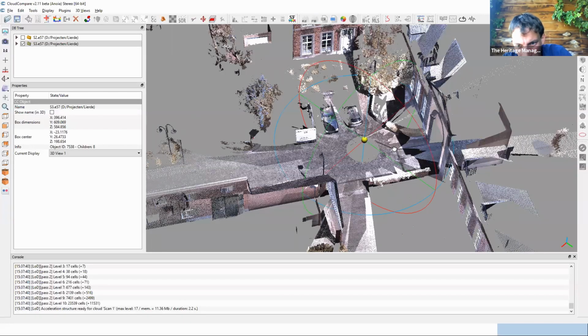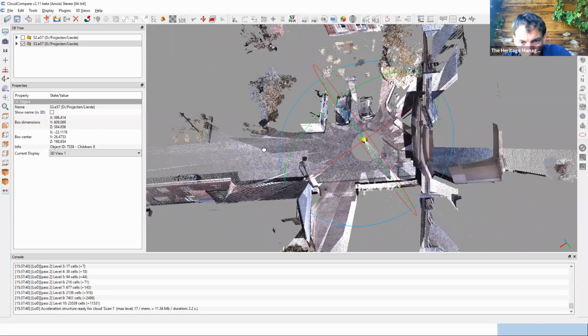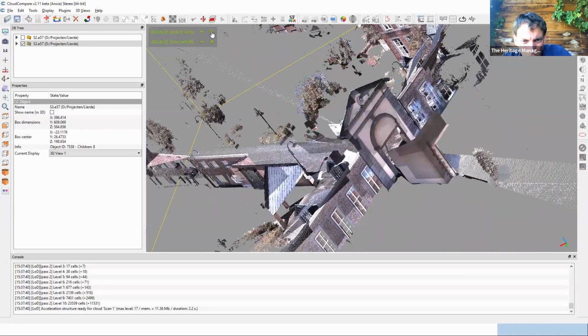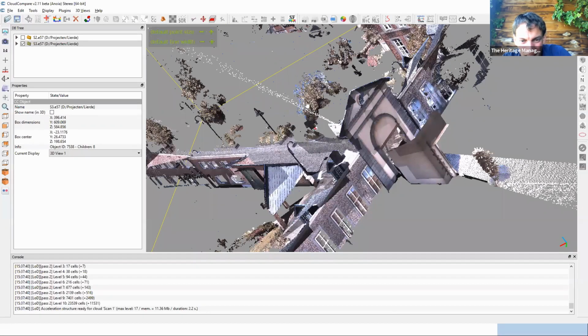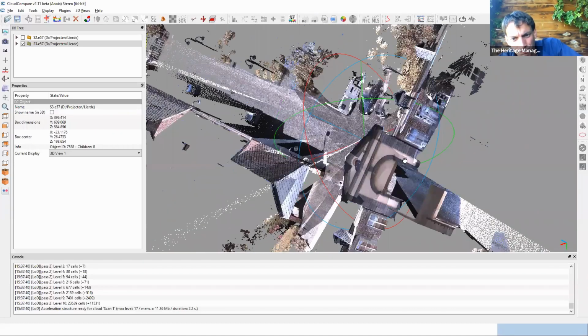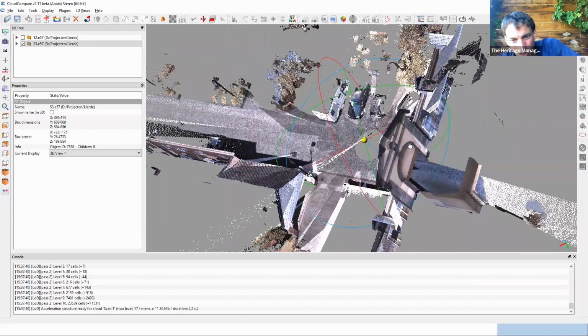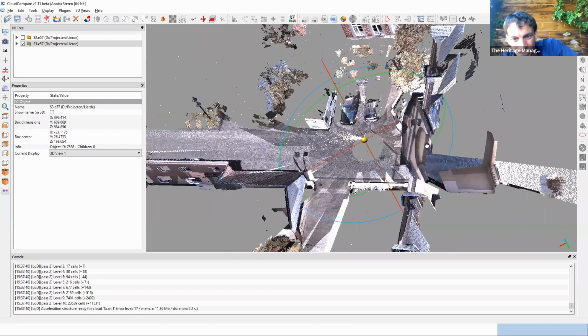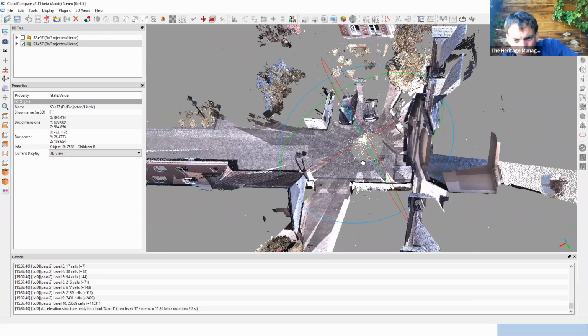And that is the reason that in many raw data sets, you will find these sparkles here. So this is actually erroneously measured data. Definitely erroneous measured data. These are just the signals coming from the sun in the exact same frequency, or in exactly the same wavelength as the scanner. And these points are actually just measured erroneously. So they are detected. You can see in this case, the sun was pointing in this direction. So this is my direction of the sun.